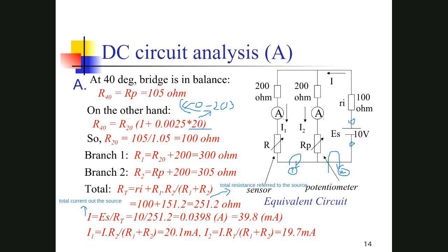This should equal to, or the student's method would directly use the Kirchhoff voltage law, minus 200 times I2, to make things clear, and minus the RB times I2 equal to 0. This is equation 1.